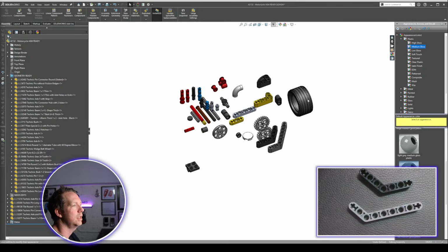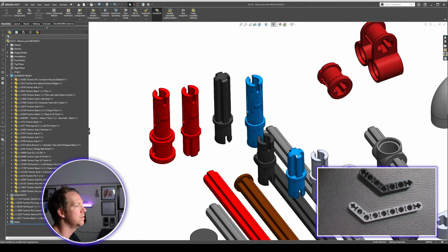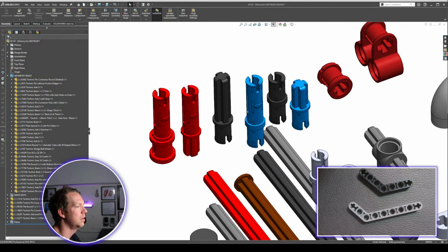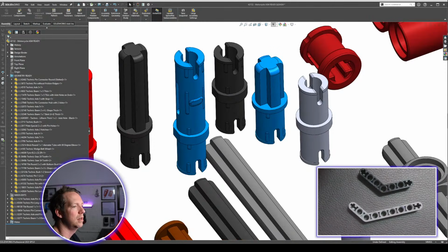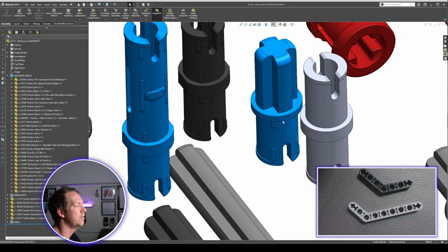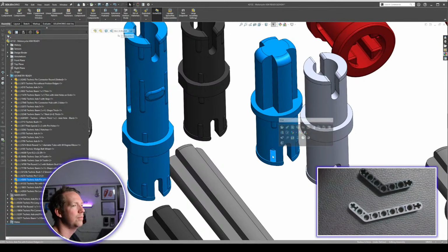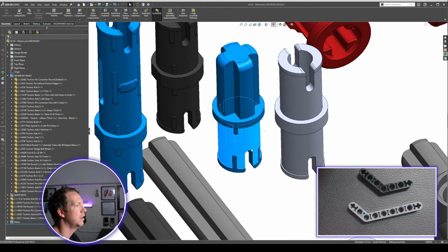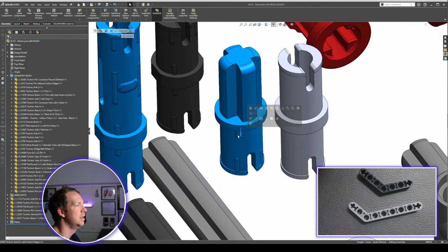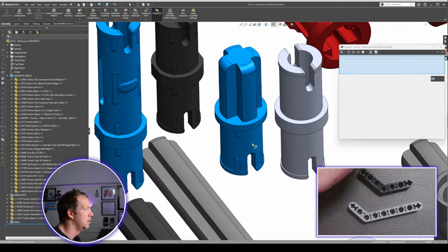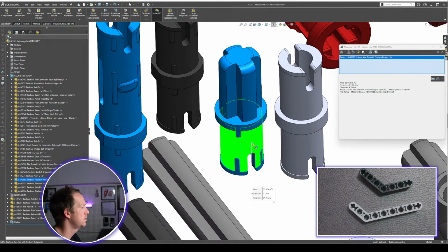Very interestingly in this series, these friction pins or these connecting pins here, you can actually see that some of them have these friction ribs on them. Like if you look at these two here, this one here is intended not to spin in the part, but this one is. And I think the height of this is about 0.15 of a millimeter. For context, the diameter of this is 4.7 millimeters.